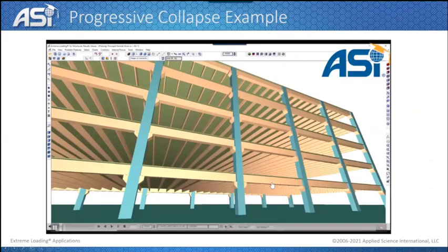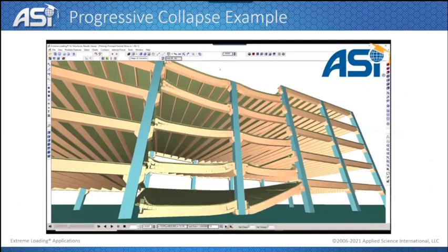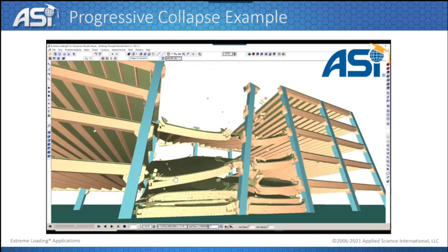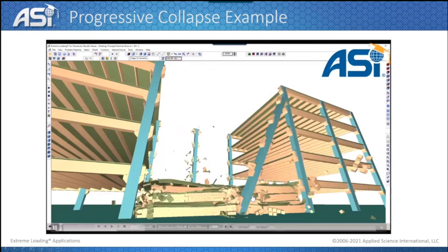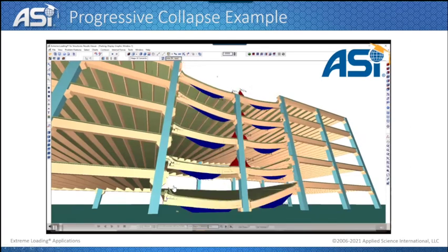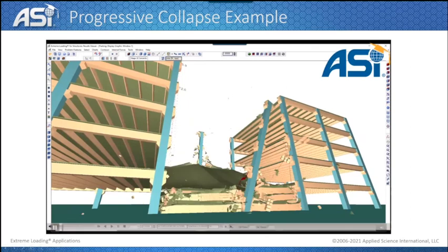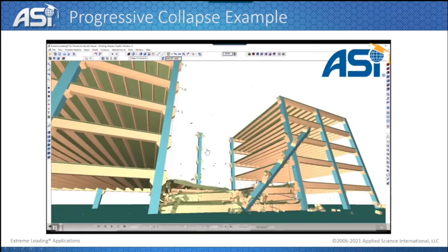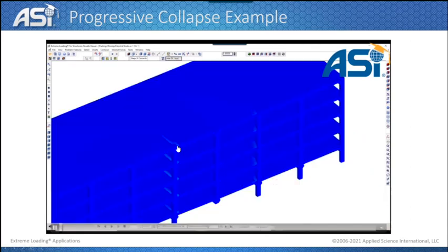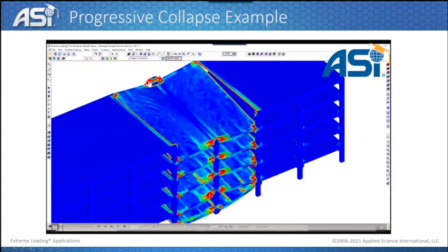Another example is a pre-stressed precast building subjected to progressive collapse, where we see failures that happened in the precast connections. And in the next video, you see the propagation of the failure along the length of the slab in here, and the punching shear failure at the back.